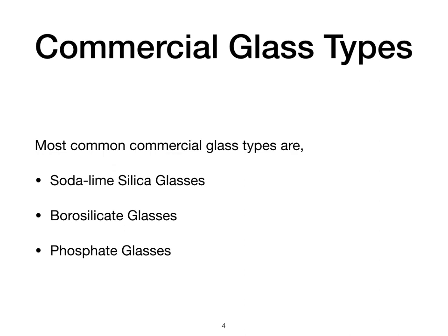Soda lime silica glass compositions account for nearly 90% of the glass manufactured in the world, which is surprisingly very high. However, soda lime silica glasses are typically not as durable as other glasses. They tend to be prone to thermal shock failure and can degrade in chemically corrosive environments.